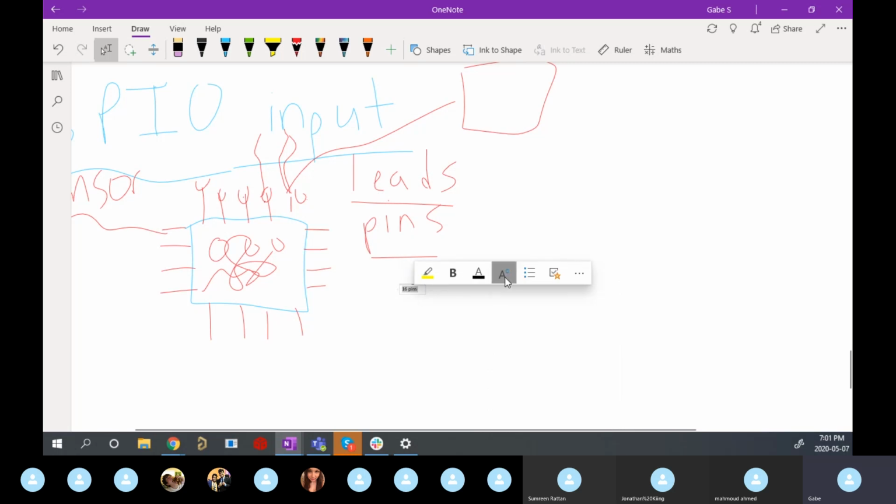The microcontroller probably has a lot more peripherals and capability than just 16 different things it can do. And so what often happens is this thing called multiplexing, right? So multiplexing is a way to connect one of these tiny little pins to multiple different building block modules within our microcontroller. So it may be a module to do our GPIO input. There may also be a module that does analog for us, or a module that does some sort of specific communication for us. That may also come out on this pin that we want to use. And so the first thing you usually have to do is connect your pin internally to whatever building block you want to use. And that's called configuring your pin.